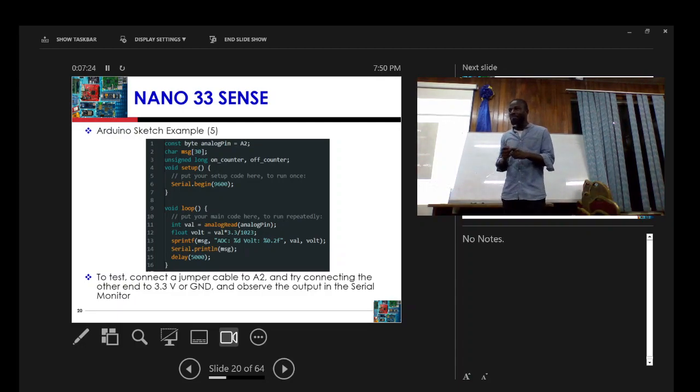The analog pin takes analog signals or it gives analog signals, and then our board is a digital board, right? The MCU does not understand analog kinds of signals. It only understands digital signals. So the analog pins will pick the analog signal, but it has an ADC. It will convert the analog to digital, and then it will give that value to the MCU, and then it will now understand it. So we have to convert it, right? Understood?